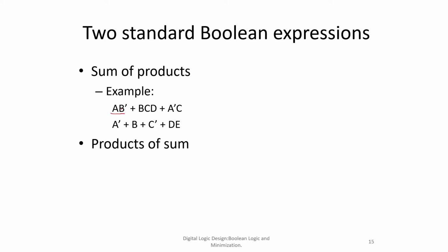So in this sum of product, we can ask whether it is a sum of product or not. Here this is a very special case of sum of product, because this is only a single literal, there is nothing else getting multiplied to it, but we can still call it a product term. And a dash plus b plus c dash plus de, because all of these terms can be denoted as a product term, it is also a sum of product expression.